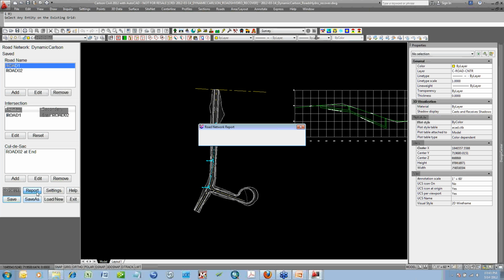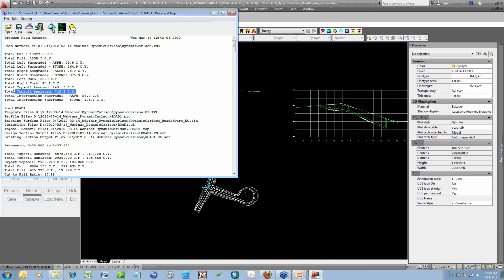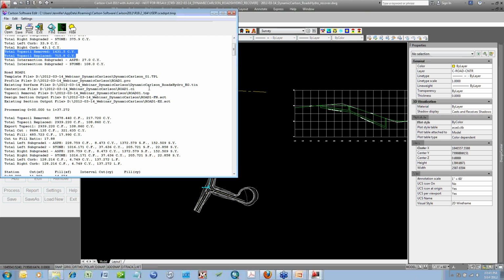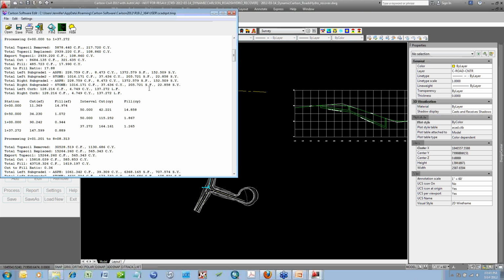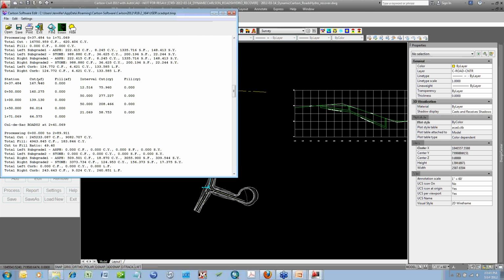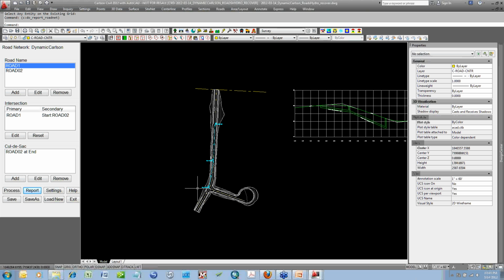And we should have checked this before, but again, we're getting some removal and replacement here for this road, but I'm not sure that we did everything that we should have done there. But again, here are the very detailed earthwork numbers that you can see. It breaks it out along the road. It breaks out intersections separately. You can see here, it breaks out the cul-de-sacs separately. So yes, stripping can be done, whether I'm the one to show you right now or not. But yes, it can be incorporated differently on each road.